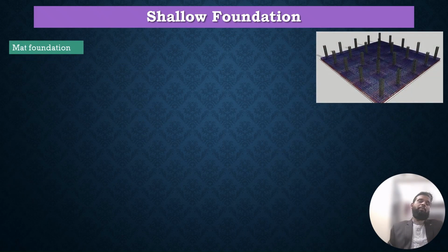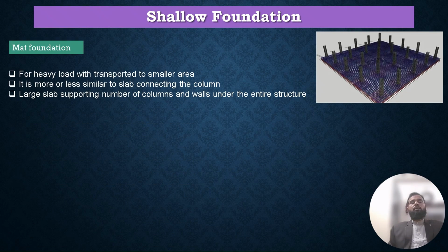Now another footing is the mat foundation. A mat foundation is normally constructed where large or heavy loads are transferred to smaller areas, and the columns are very closely spaced, so we have to transfer the huge load to the ground. It is similar to a slab connecting the columns.